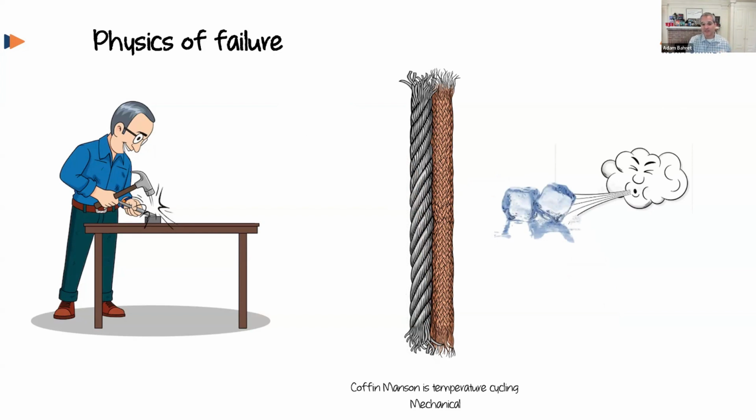For that, a very common model is the Coffin-Manson model, which uses temperature cycling in an elevated, more extreme range to compress the time it would take for that fatigue to cause failure in a normal use case. So you could take, for example, 10 years of cycling fatigue for a product that is outside and goes from daytime to nighttime, so every 24 hours it does a full cycle, and compress that to a few months by using a greater temperature range, and use the Coffin-Manson model to extrapolate it out to the full life.